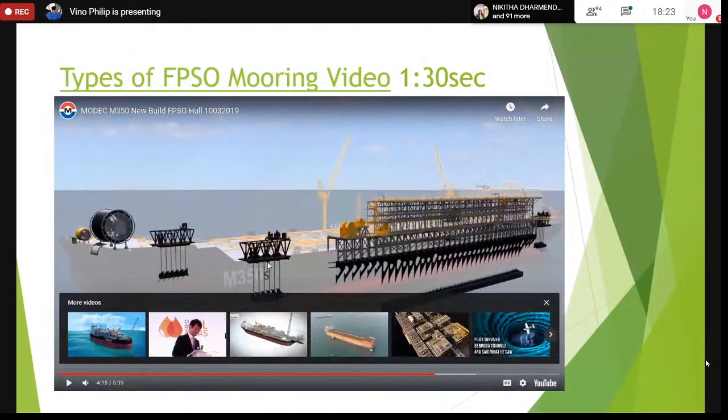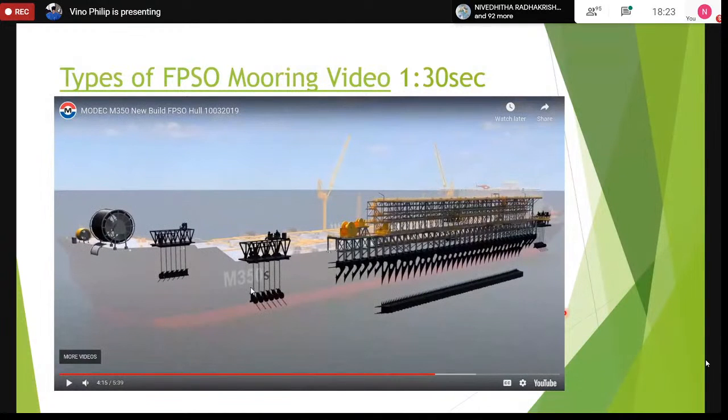So this is the mooring support structure called spread mooring. These lines on the corners of the vessel are the mooring lines. Here it is 1, 2, 3, 4, 5, 6. So this is a 6x4 mooring design configuration. And over here there are 6. Over here there will be 6. And at the back end there will be 6.